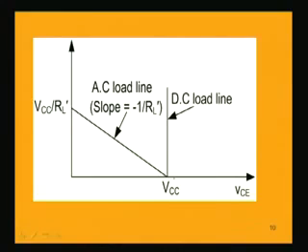Now, in this type of push-pull amplifier, what we have seen is that one transistor is operating at a time. So, we are combining the operations of two transistors, and finally, we are finding out the output voltage by combining these two voltages which are induced individually by the two transistors in each half cycle. At a time, only one transistor is conducting. So, now if we consider the AC load line, then for one transistor, it will be like this.